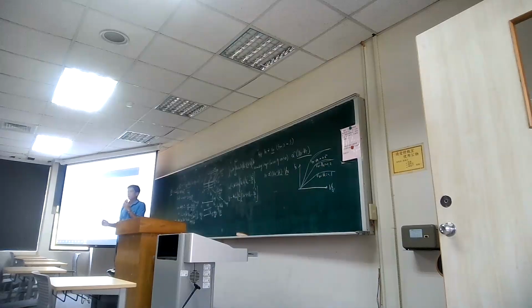In the triode region, initially it is linearly dependent on VGS minus VT and VDS. But later on, it will be in the saturation region. For instance, in the triode region, VDS is much smaller than VGS minus VT. So the equation of the drain current ID equals the equation we derived here.